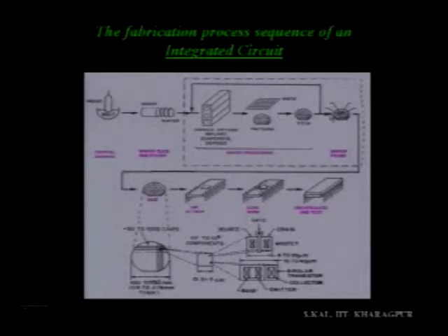After that it is coming here the finished wafer, and there you can see some pins are coming, and using these pins we are testing the chips. That is wafer level testing. And in this wafer level testing we select the good chips, and then it comes here the dice. This is the dice. So in this dice, the good chips are already marked, and then you have separated the dice. It is shown here in an expanded version. You see each square is a small chip, and that looks like here.